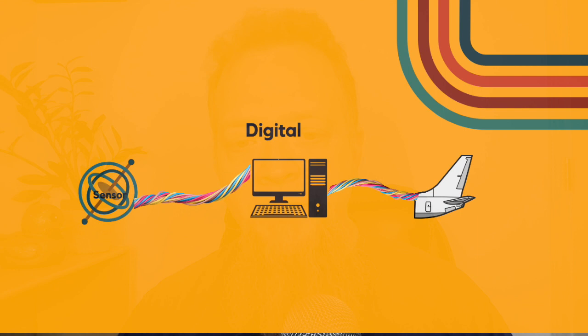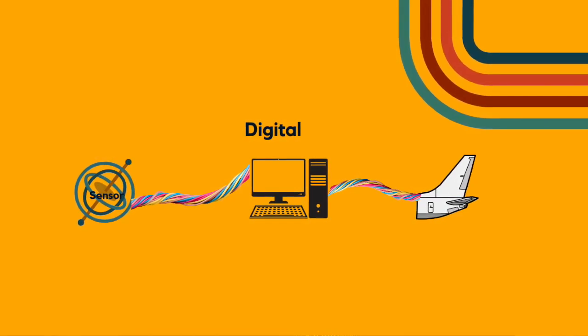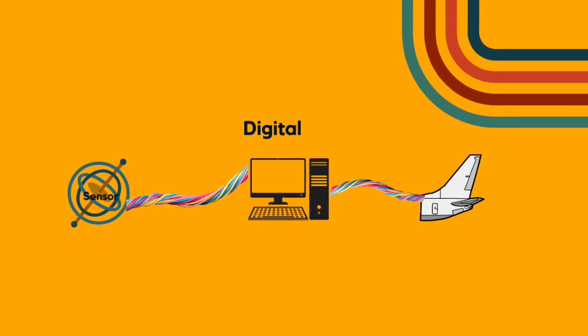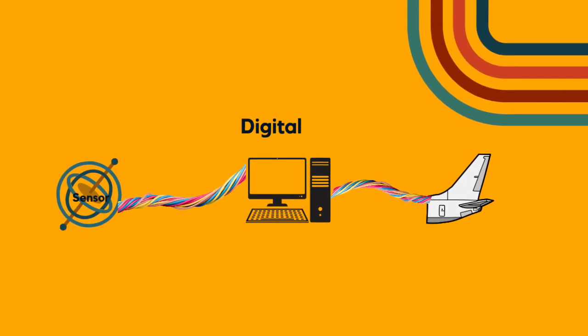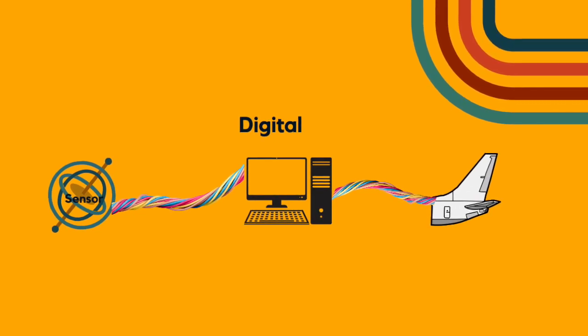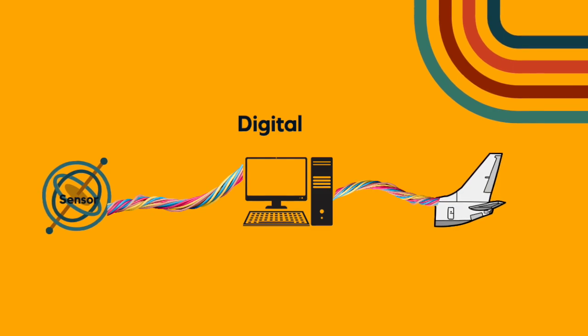Now we're talking about digital computing. So now there's a computer in the middle, a flight computer, let's call it. The gyroscope itself is still an analog system, but you'd have a little computer in there that would digitize those readings. Instead of getting a physical movement or a voltage coming off it that could vary over a particular range, now you have a discrete number coming out, and that's encoded in binary, in ones and zeros, and I'll talk about that for a second.